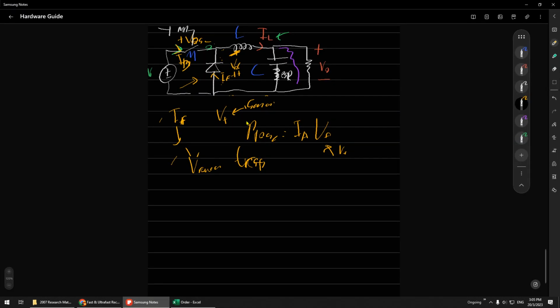I think no need to explain again. For the current, you have to look during the simulation. You have to put the current sensor during the operation with the highest current. When the current is high, you have to measure it, and then measure the voltage, and record the highest voltage. Then you multiply by the safety factor. For this case, I suggest 1.3 to 2 times. Higher is better, but usually higher means more expensive.